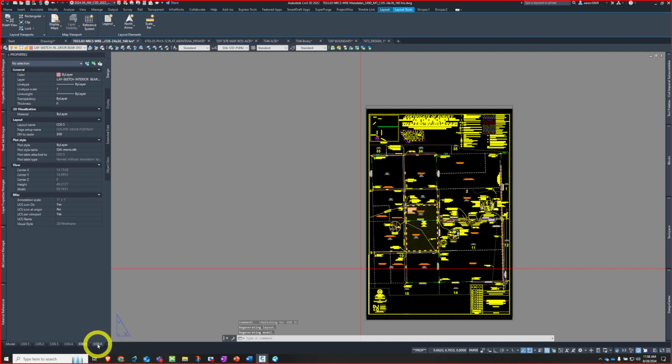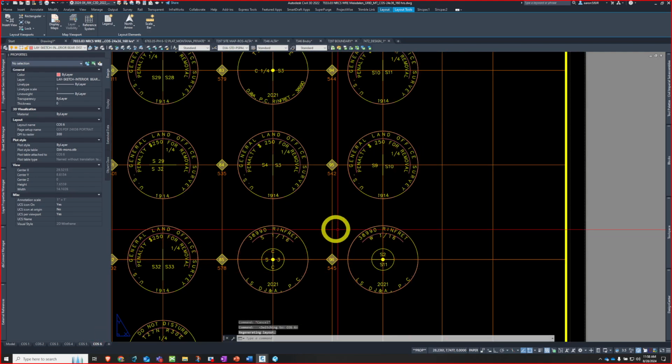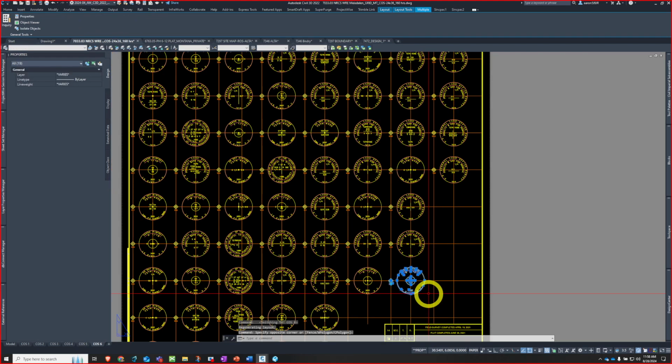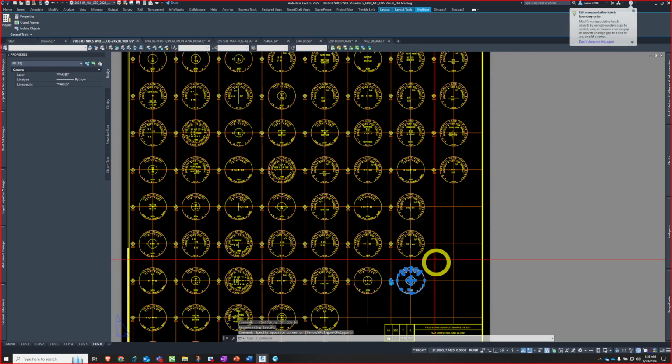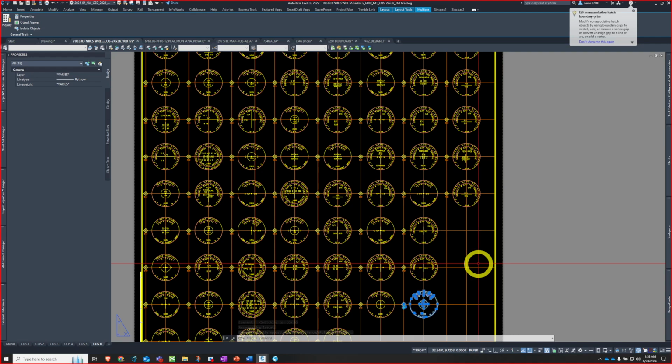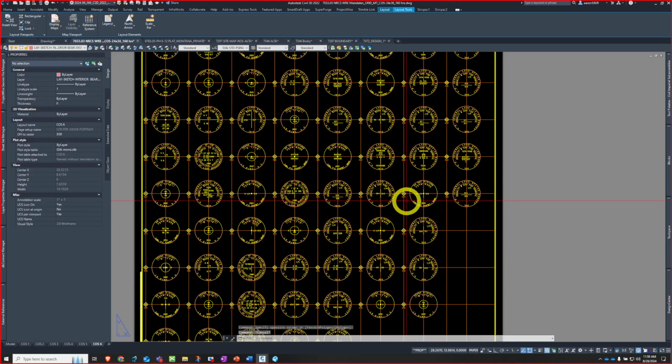So this would be a good example to pluck from. We had to draft a whole pile of them in paper space. Those just work. The architects like to blow up if you go from model to paper, but if you go the other way, it works fine. So that's some tips on those. I try to do those in paper space whenever possible, and then I can move them to model space as needed from that point.